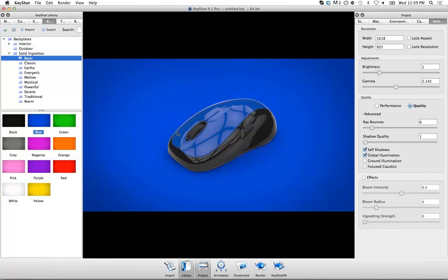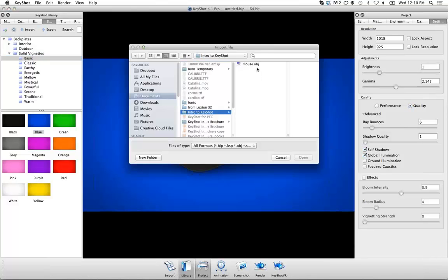I have a question from James. James wants to know, is the up orientation and setting specific to the modeling application that is being imported? Here's the second part. If I import from SKP, I need to use orientation on Z. If I use Y option, it's on its side. Yeah, so change it to whatever the up orientation is for your 3D application. It kind of changes from one application to the next. So that's why KeyShot allows that pull down, make sure you set it when you want to import something.